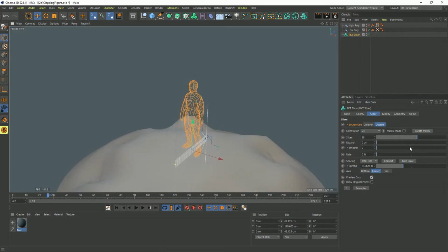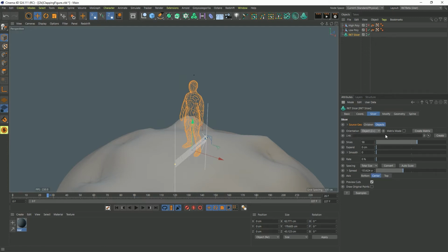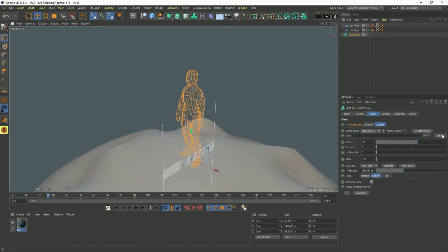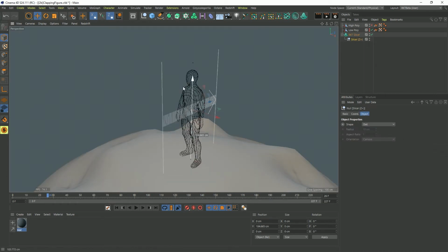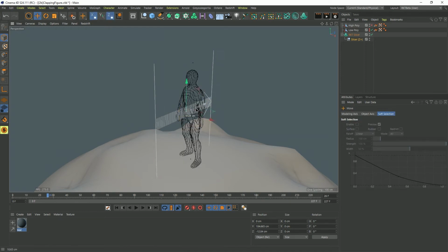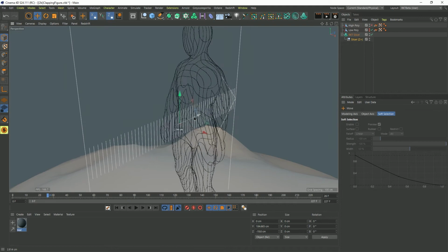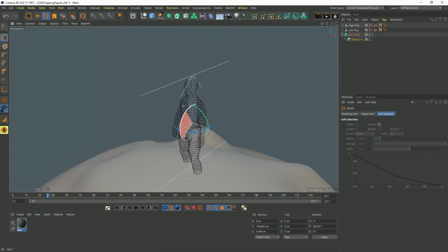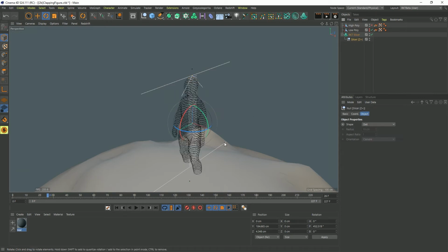There's actually one last orientation, and that is object Z plus. Creating that, it will make a link field for you, and you can link any object in there that you want. But in this case, I don't have an object to link to, so I can hit create, and that will make a null for us with an appropriate name. Selecting that, I can now take that and move it anywhere I want. So I could scoot it forward and backward. You can see, if I do it slowly, we can see these different cuts passing through the model. We can also hit R for rotate and spin that and get cuts exactly where we place them. So now we are able to, independent of the actual slicer object, move their placement, their center point, and their orientation by rotating it. And that's all by using this null.